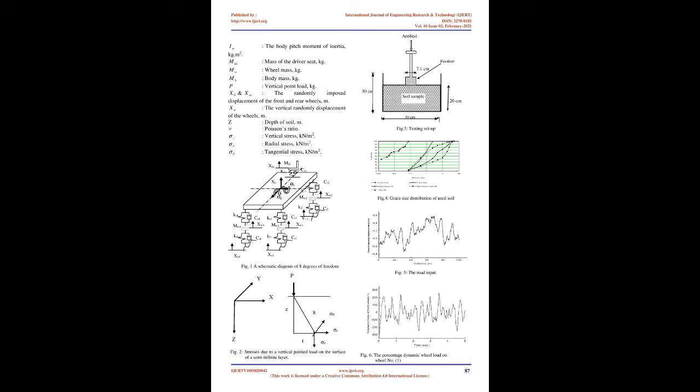Materials used. A number of bearing capacity tests were performed in the laboratory on 5 types of soil to analyze the load applied, contact area, soil depth and settlement of soil due to the applied load. In the present experiments 5 types of materials have been used. Silty clay, coarse sand, stoned lime, sandy gravel, and gravel sand are the forms. These soils are used on the unpaved road as base layer. Tests were performed to determine the physical characteristics of these soil types. Figure 4 shows the grain distribution curves and Table 1 shows the physical properties measured for the various soils used for the experiments.